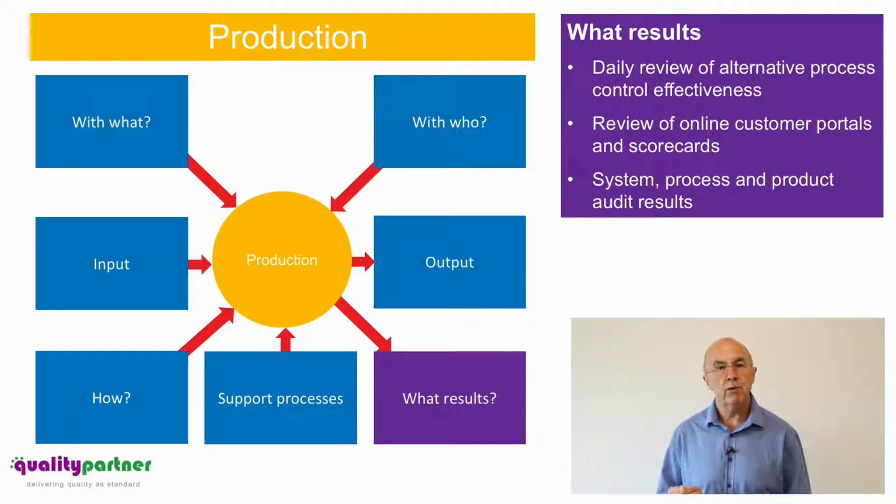And for example, the people that are doing process audits of the manufacturing process, they are competent to use the FMEA to make sure the organisation is complying with the requirements in the FMEA and we're achieving the desired results, and also that they're using the control plan and we're making sure that all the controls that we've got in the control plan have been effectively implemented. Those documents need to be an essential part of undertaking a manufacturing process audit.